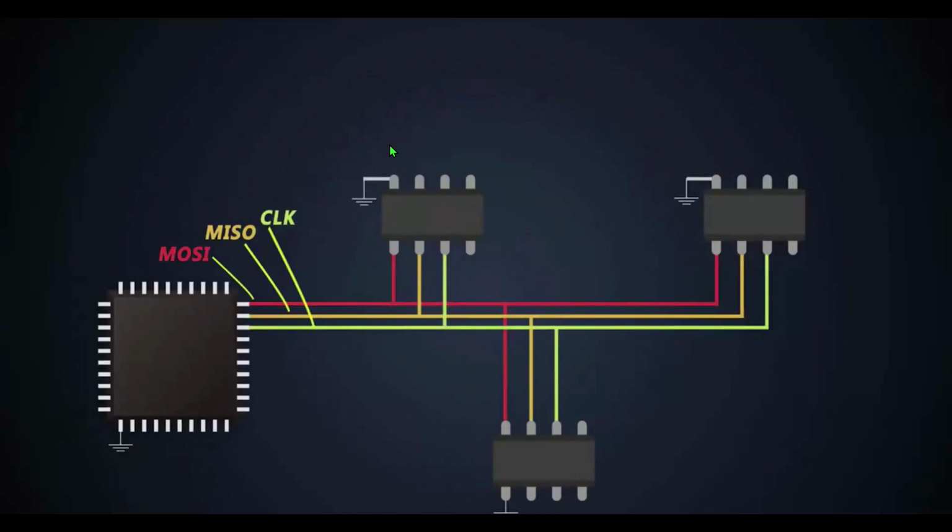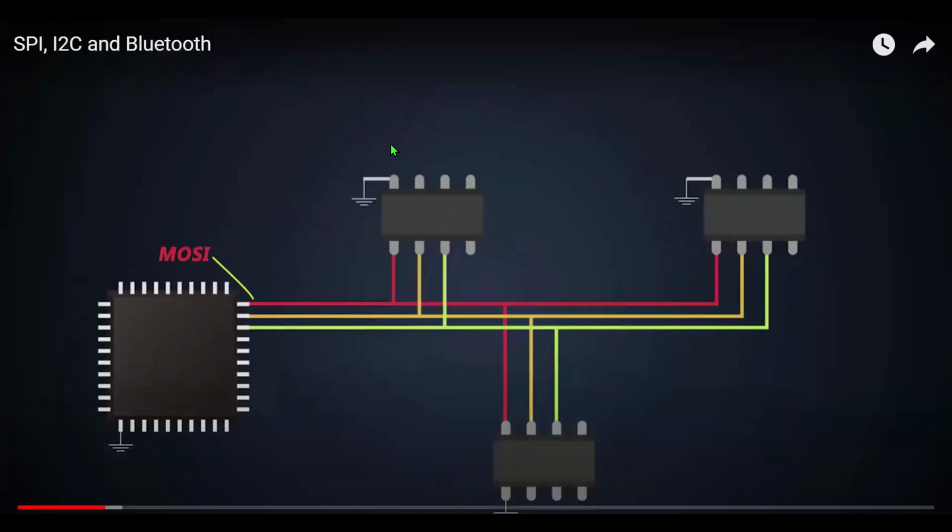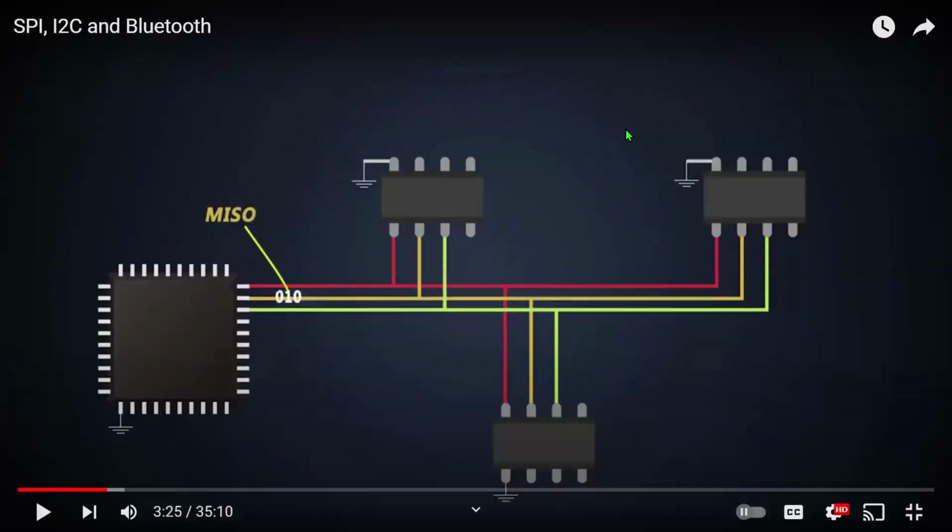As per the name, MOSI means the master sends data to the slave and the slave receives that data. On the MISO line, the slave sends the data and the master receives. So here you can understand how the binary data is transferred. Yesterday I explained it in the session, but I didn't start the practical. So how is the binary data transferred? Like this is your microcontroller. If you connect any other IC, how will the microcontroller data be transferred?